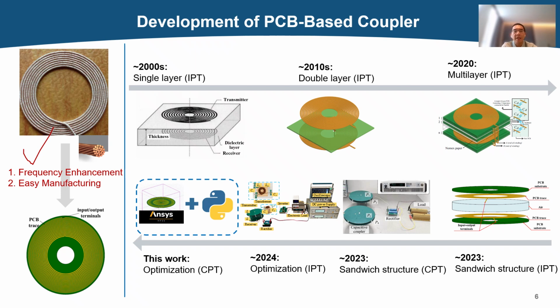Also, in 2023, this sandwich structure PCB-based coupler was successfully validated for CPT applications. The roles of components were reversed. The compensating capacitors and coupled inductors in IPT systems were repurposed as coupled capacitors and compensating inductors for CPT systems. However, optimization of such CPT couplers has not yet been explored in existing literature, and this work aims to fill that gap by proposing a two-stage optimization method to reduce the equivalent series resistance and improve the system performance.